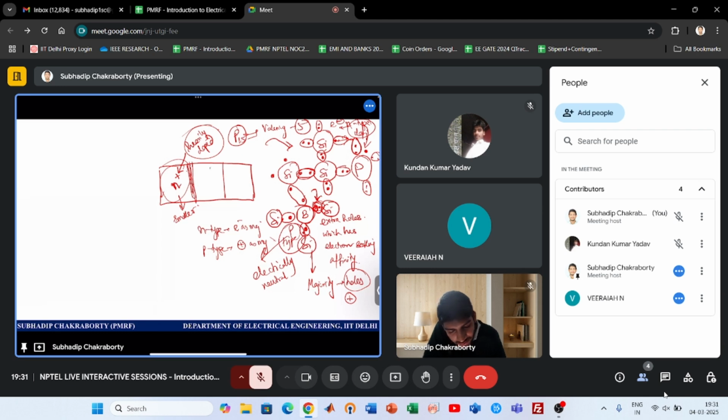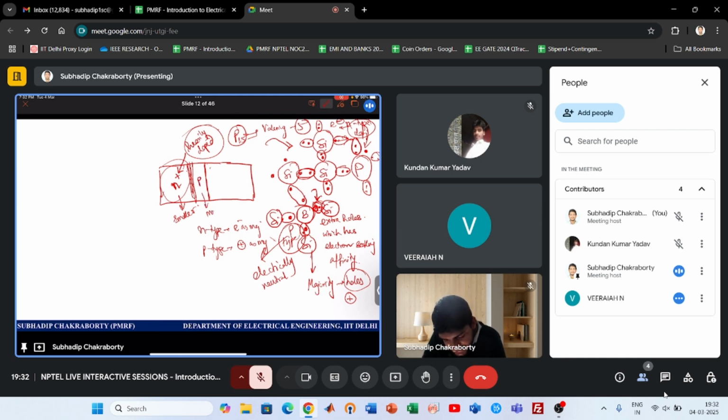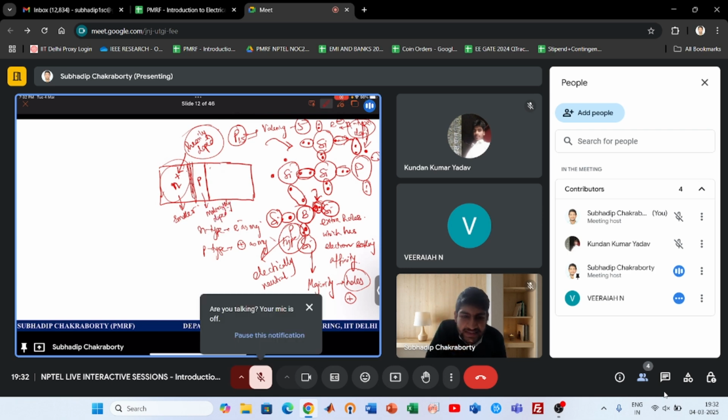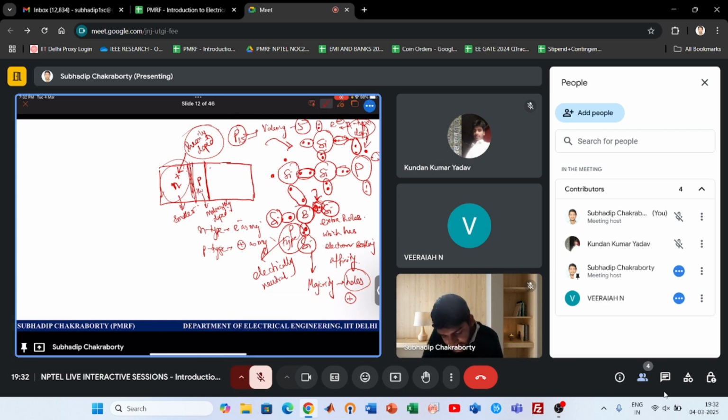And this base, I will draw it correctly. Let us create a narrow section and lightly doped, right? Relatively, moderately, I can say, moderately doped p. That's why I did not place any plus or minus sign, which indicates it is moderately doped, but a thin region, not much. This is thin, right? And one is actually a bigger portion of the wafer, which is very lightly doped.